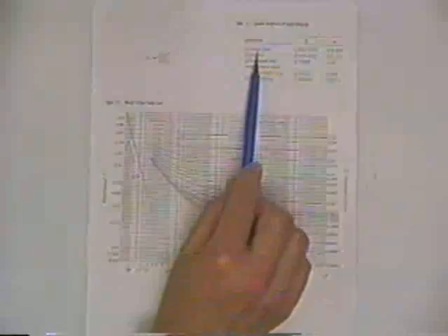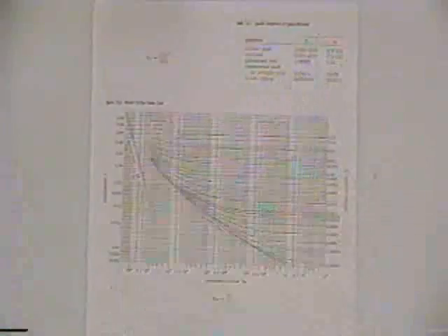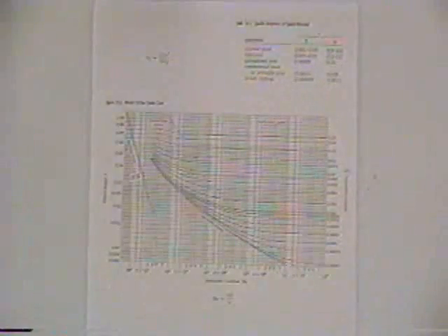And of course, the rougher the pipe, the more head loss you would anticipate. And so in your reference manual, you'll find a very brief table, and other references are very extensive tables that for different types of pipe give you the roughnesses in either meters or in feet. Now if you've got a rough pipe, but it's a big pipe with a large diameter, it's going to have a different effect on the flow if it's the same pipe material, the same amount of roughness represented by the epsilon, but a smaller diameter.